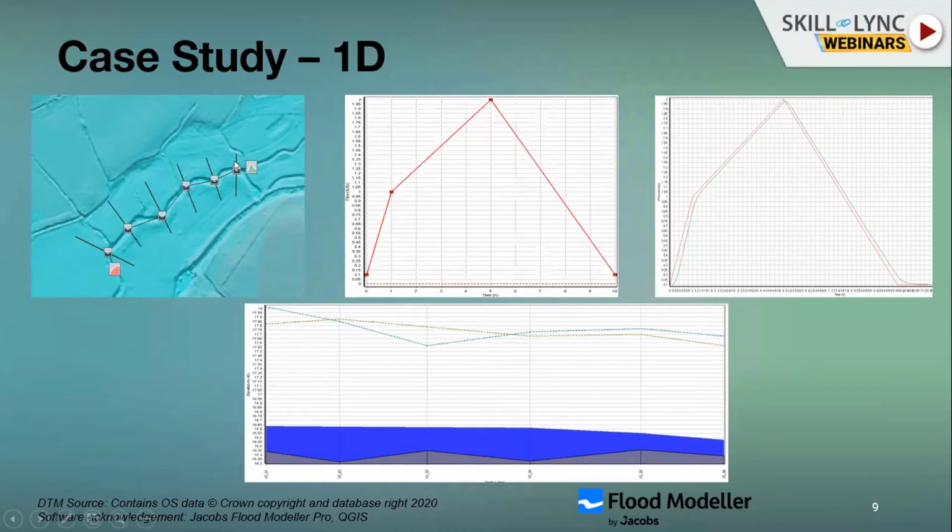Initial conditions are necessary because there will be some existing water, or some existing flow in it. So the initial conditions are required. These are the five boxes while building any 1D, 2D, or 3D model. I'll repeat that again: first is general, second is geometry, third is upstream boundary condition, fourth is downstream boundary condition, and fifth is initial condition. You should be aware of these five things while building a model.